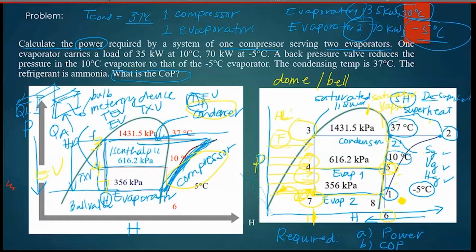The refrigerant has to enter the suction port of the compressor, and it will be compressed until it reaches 2 at a superheat region. So the one involving the work of compression is 2 and 1. 2 is higher, so it's positive, no? H2 minus H1 times mass, and that's going to give us the work of compression.